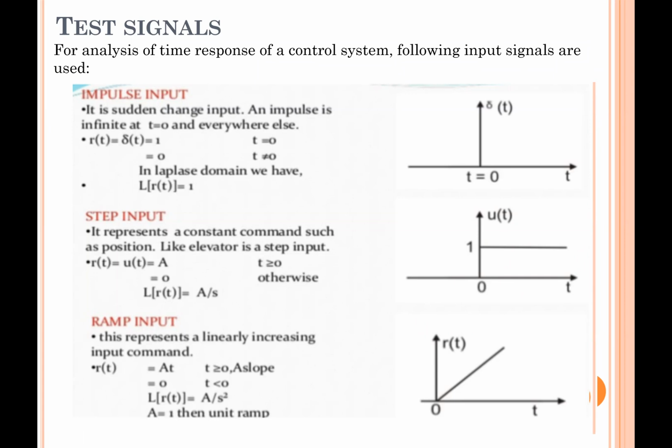That is, all kinds of signals in the field can be mathematically represented as some combination of these test signals. Okay, this particular thing comes from the maths domain, so we are just taking advantage of the things that have been developed there already. So that is why we have developed these test signals: if our system is giving the desired output for test signals, it is expected that for any real-time live signal coming from the field, it will behave as expected.